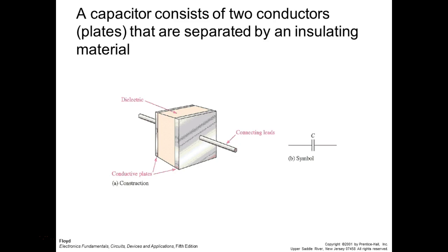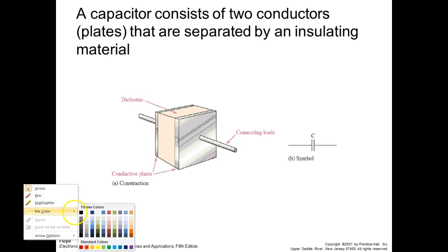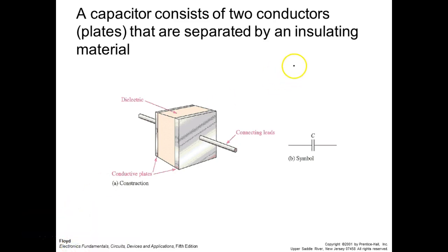So this is the symbol for a capacitor. Now normally, that's why I like to use this symbol right here, guys. So this is one of the symbols. The other symbol we can use is this guy. And this is the one I like to use because you can't confuse it for a normally open contact. But you're going to run into both of them.